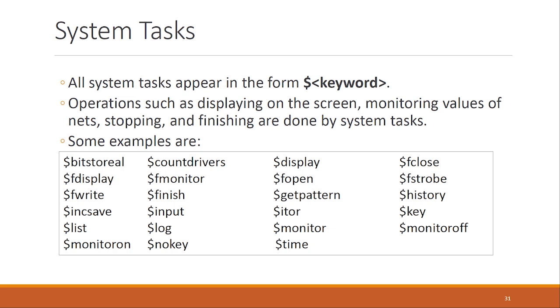In our labs we will use the system tasks $display and $monitor to display something or show an output to the user. And when you want to finish the simulation after a certain time, then you can use this $finish system task. So when we are actually using them, you will understand these things better.